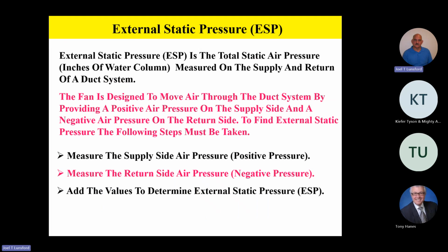So once we build a duct system, we're going to have some method of commissioning that duct system. And so we're going to teach you two different methods now. Actually, it'll be a third method because we learned earlier yesterday that we could use a rotating vane anemometer, the little whizzy wheel guy, or a hot wire anemometer, and we can actually put it into the ductwork, or take the register off or what have you, and we could determine airflow by measuring the duct size and measuring the velocity of the air. And we went through all that yesterday, and that's a good way to do that.